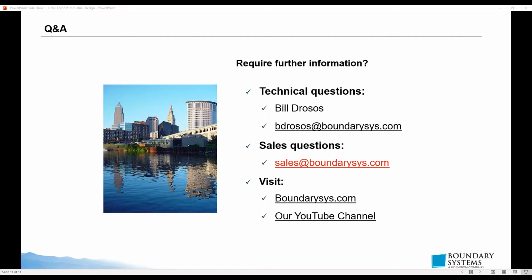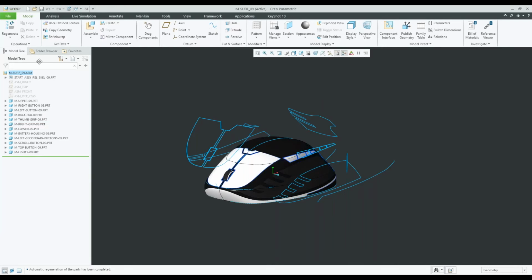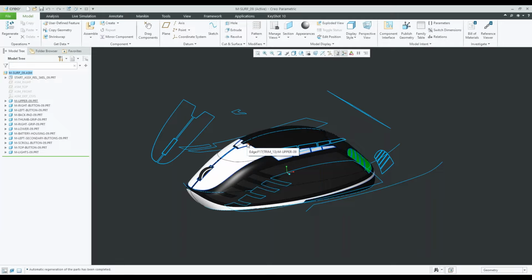Why use the skeleton versus the master merge? Well, for me, that's just typically how I've done it. It's been helpful for me to create the skeleton part. Another thing that's good about it is that the skeleton component, if you guys use Windchill, isn't going to show up on your production BOM or your manufacturing BOM.